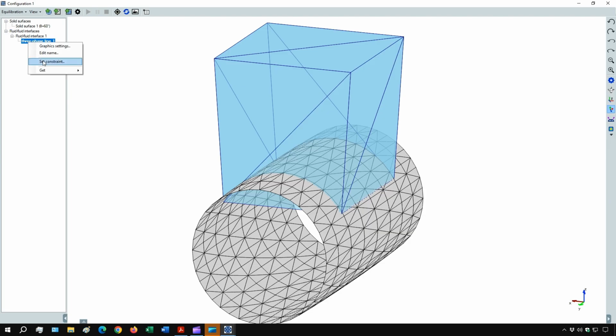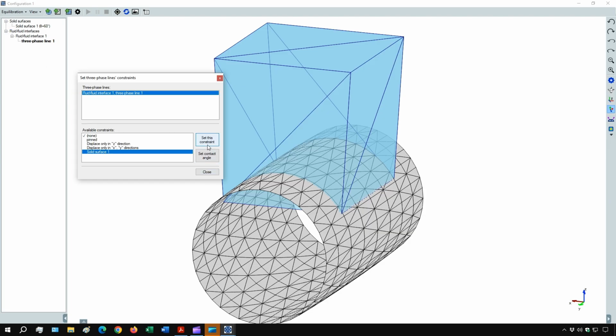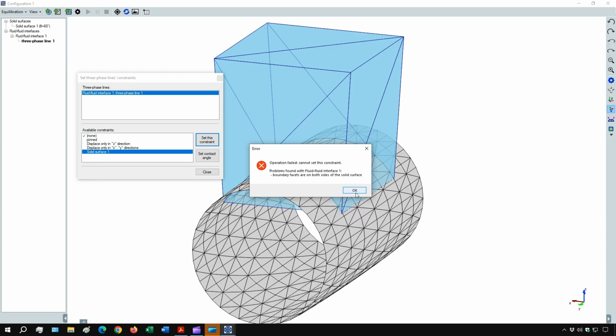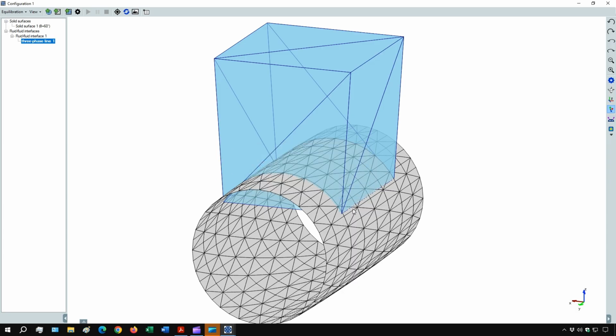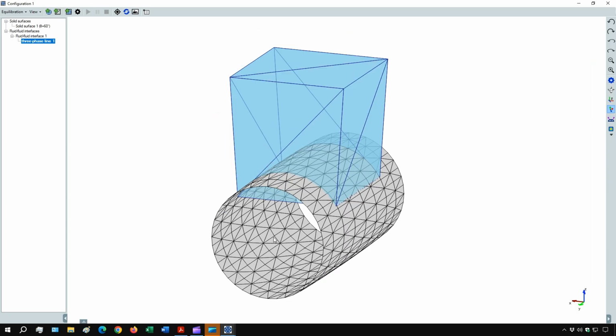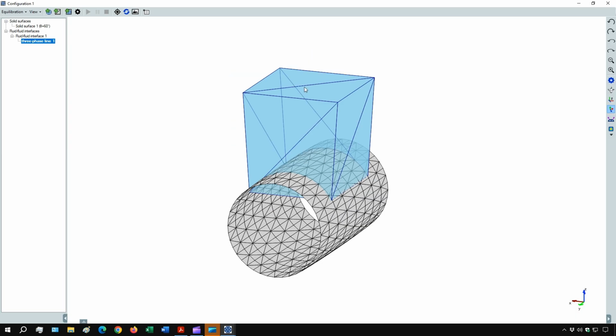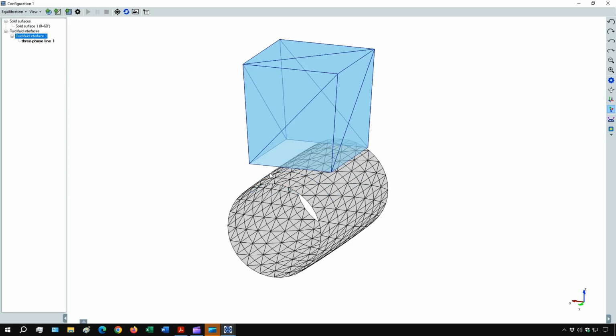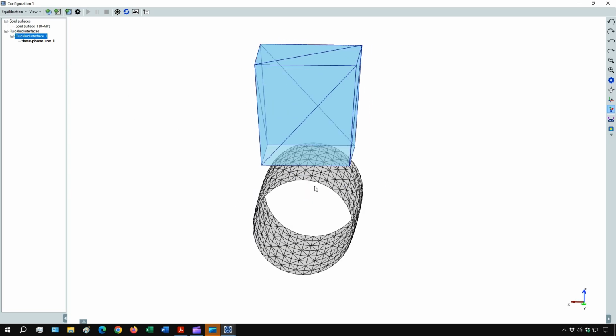As we saw before, for this fluid interface mesh shape, I cannot set the cylinder as constraint for the fluid interface boundary. Instead of editing the mesh shape like we did before, I can simply try to displace the mesh opportunely in a different position, and then try to reselect the cylinder as constraint for its boundary.